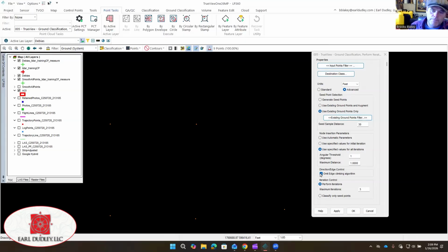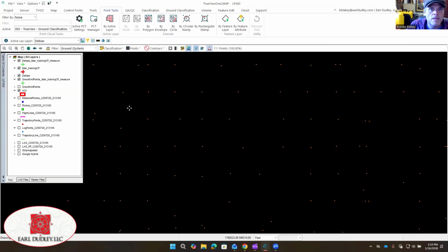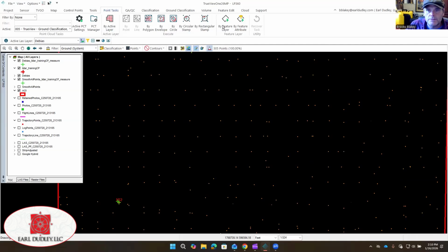So by starting out with a really low angular threshold, that's going to all but guarantee we don't classify vegetation, versus if I had, say, a 5-degree angular threshold or 10 degrees. We're going to start out with 1, see how that works out for us, and we'll go from there. So I'm just going to hit apply and close this out. And we're going to execute by feature layer again. Again, we only want to run this in our area of interest.